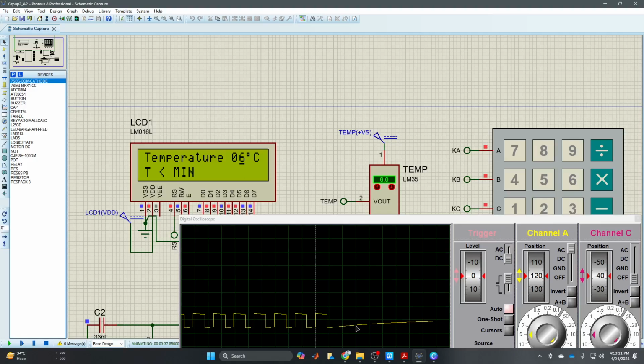See, this has become 0 volt. And now when we look, we are getting a wave shape. For almost 50% of the time it is 5 volt, and for the rest of the time it is low, if this is our time period from here to here. So for 50% of the period it is high, and for 50% it is low.